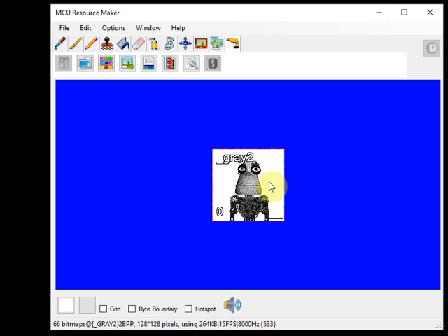If you've got, say, a 320 by 240, then you should be able to show it in, say, 1 bit per pixel quite easily, or 2 bits per pixel, even 4. It really depends on how fast you can get your SPI bus moving.